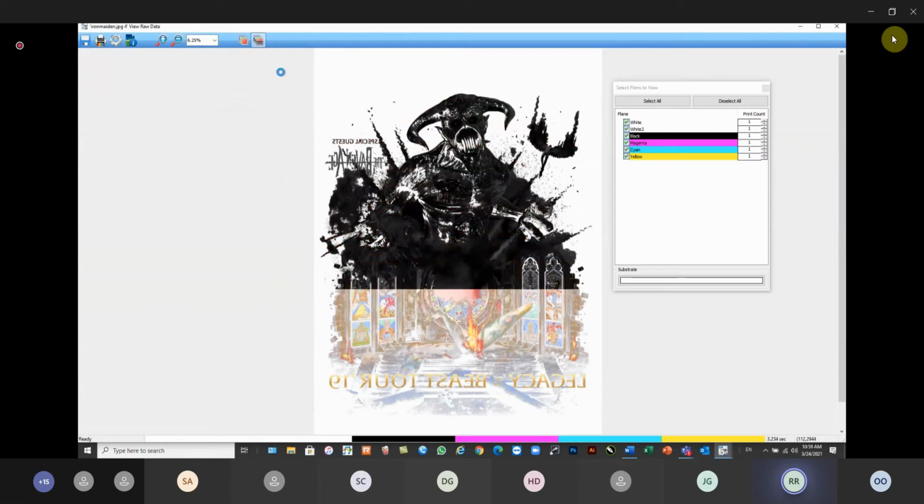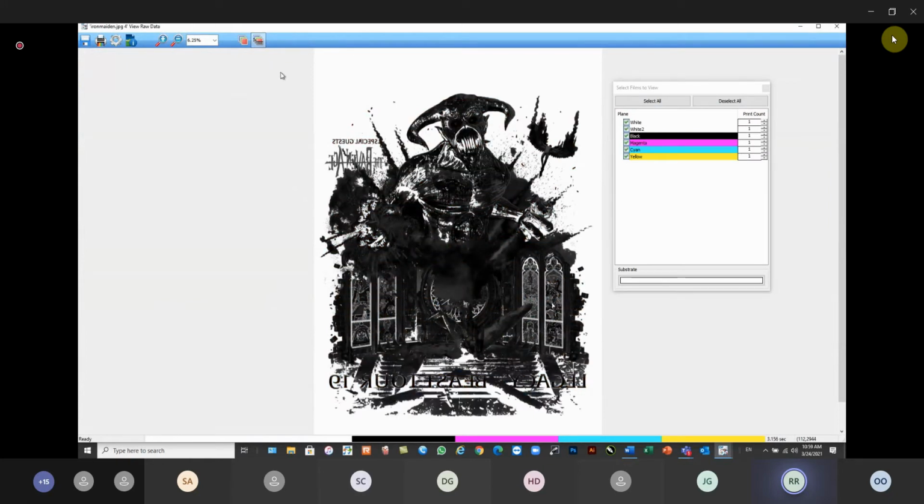This is going to print everything, basically a white base over everything, all the dots and everything. Now on some garments, for instance on white garments, this is going to give you a really nice punchy image. Even on a black garment, it's going to give you more punch because you've got more opacity, more white ink being laid down, but you're going to get more of that screen printed feel, almost like a vinyl transfer type feel and look to it.